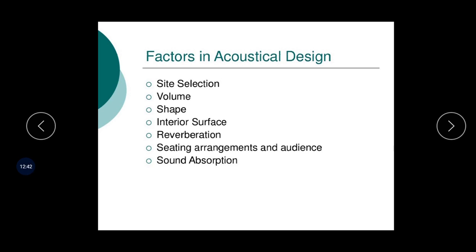Ceiling splays, or spread outs, and appropriately tilted portions of the ceiling can be arranged to reinforce the sound. In case of long halls, all reflections of the original sound must reach the listener within 45 milliseconds of the direct sound. Any sound reaching a person after 45 milliseconds of the arrival of direct sound will be heard as an echo.